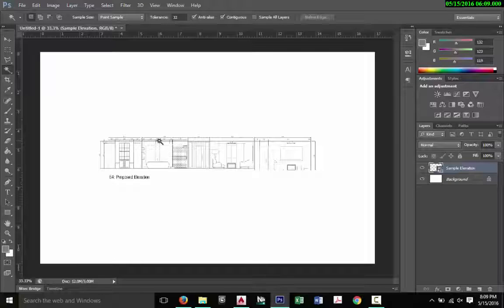So if you bring it in and you've already set up for the paper and everything and it looks tiny, that's fine. Let's assume you were doing other things on this sheet. I would never present a drawing this tiny on this big piece of paper. But just know that this is in scale right now. So if you were to print this out, this would be at the 1/4 inch scale that I printed to. So be sure that if you're trying to stay in scale, that you're not adjusting the size of this image.